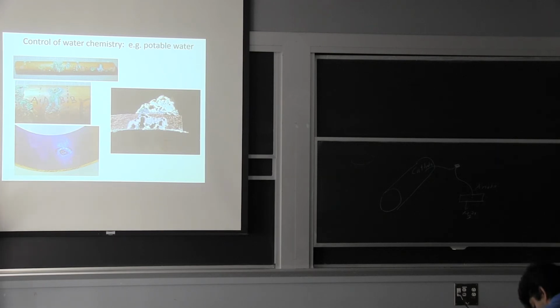If you have too much flow, you're eroding away that very thin protective layer, and then you start having regular unprotected corrosion. If you have a particle in your system, any debris from the burner or anything like it, you create a local condition, and that's what can create, if you remember the crevice corrosion system, a different environment under the deposit than on the side of it. So you start that reaction and it will continue. And that's why after the fact you see these holes.